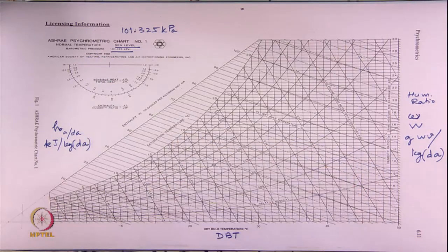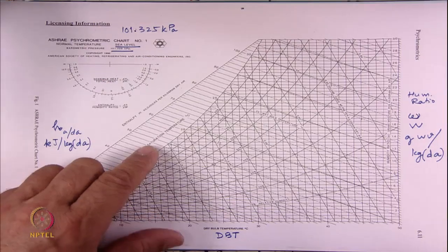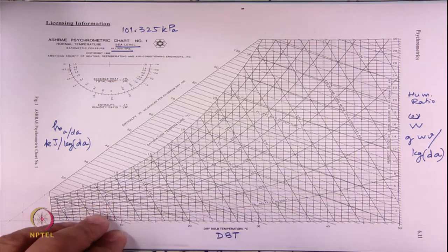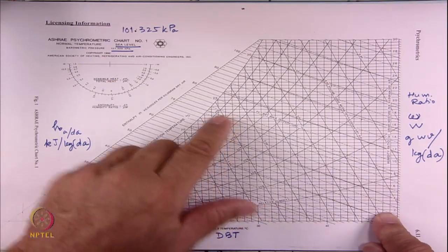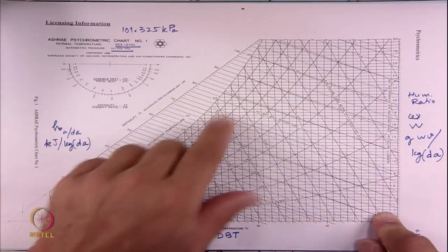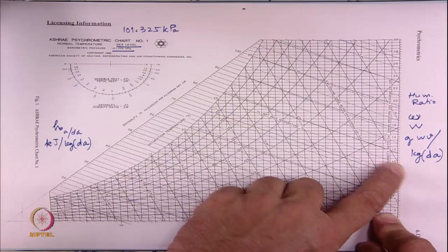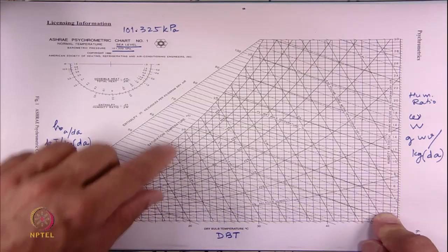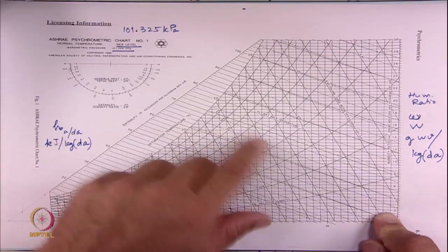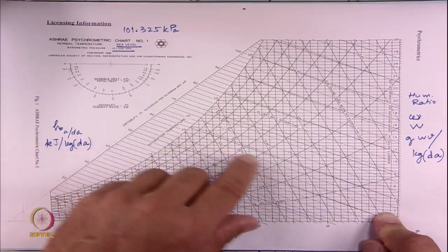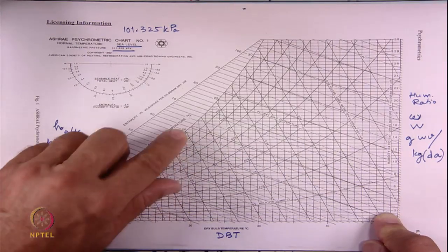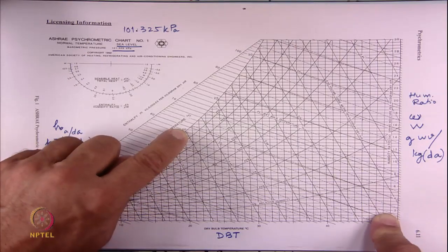That is what saturation temperature is. And then we saw lines of constant humidity 90, 80, 70 like that. And then we got these lines, which are your wet bulb temperature lines here, and this has exactly the same magnitude as the DBT, and you can see that the 20 degree WBT line here starts at the point where the 20 degree DBT line meets the saturated state.